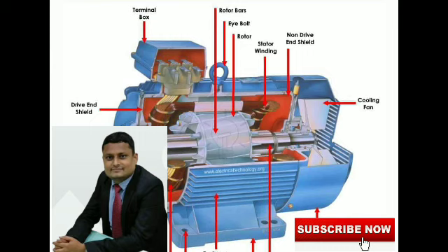So for the area of a stator slot, the slot liner must be 0.5 to 0.7 mm. Coil separator length is 0.5 to 0.7 mm for LV and 0.8 to 1.2 mm for HV. Wedge is 3.5 to 5 mm, and the lip will be 1.0 to 2.0 mm.